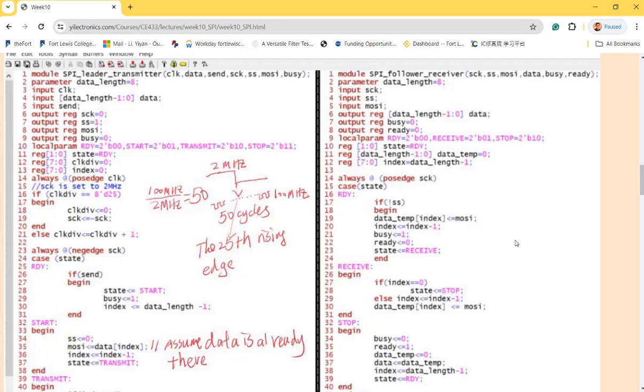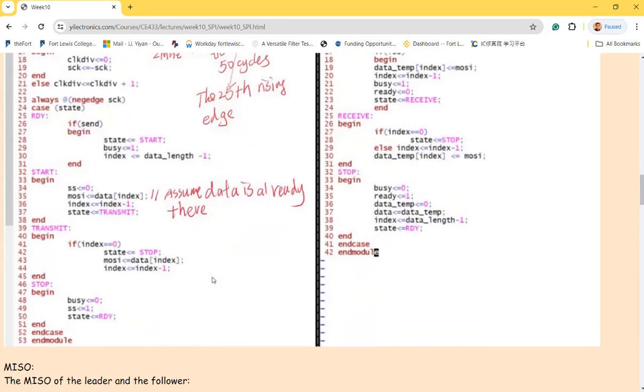Okay? When you communicate with Arduino's SPI, you need to look at the data sheet and configure all the phase and clock polarities. Probably not clock polarity. I don't know if you need to do that as well. Maybe. But you can always change it. You can either change it here in your ASIC, your chip design, or you can change it in Arduino settings, which is just the software. I believe there's a register you can write to that controls the configuration of the SPI mode. Okay.